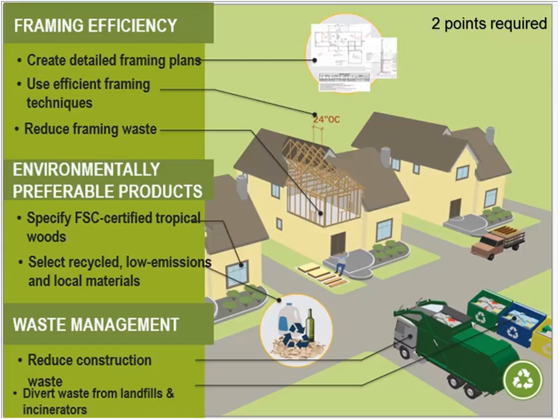Reducing framing waste on site is important in this section. This is also the section where it specifies that you must have FSC certified wood if you're using tropical wood, so that's really non-Canadian or non-US wood. That's really important that you do that. SFI, Sustainable Forestry Initiative, I think, is not allowed in LEED right now, but I did hear that they're becoming a lot better. So maybe check back on that.